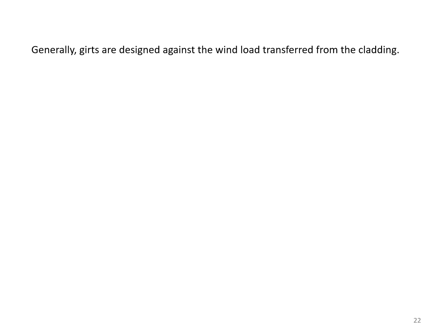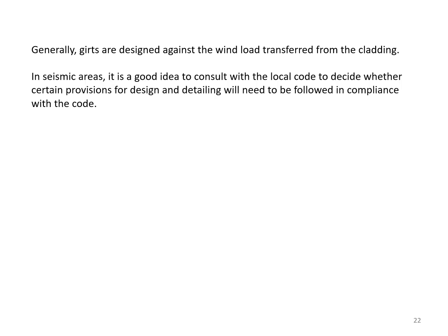Generally, girts are designed against the wind load transferred from the cladding, as we saw in our example. In seismic areas, it is a good idea to consult with the local code to decide whether certain provisions for design and detailing will need to be followed in compliance with the code.